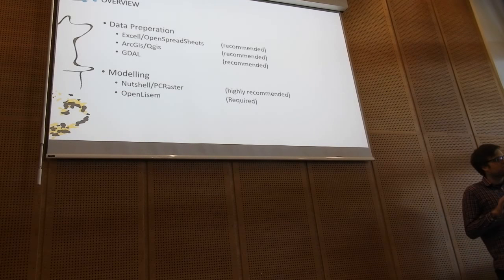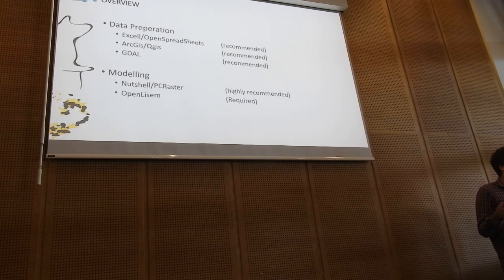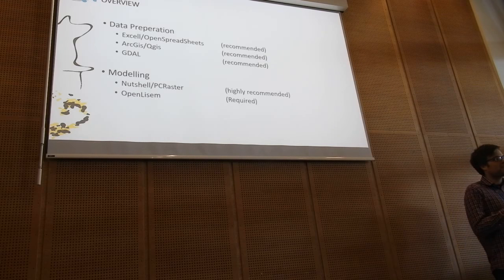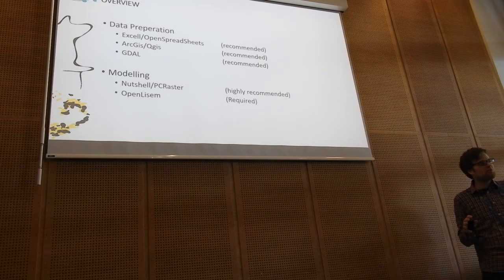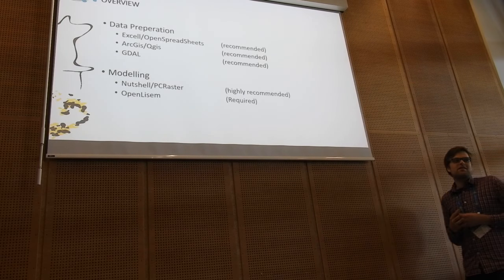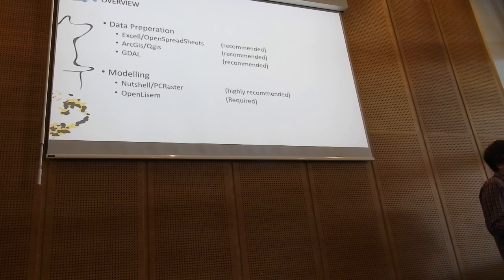GDAL has built-in support for the PCRaster map format, which is the map format that we use by default. You don't have to use it. You can import and export GeoTIFFs into LISEM or any other format that GDAL supports. However, typically we do our data preparation in a free GIS called PCRaster, and QGIS has built-in support for PCRaster maps.